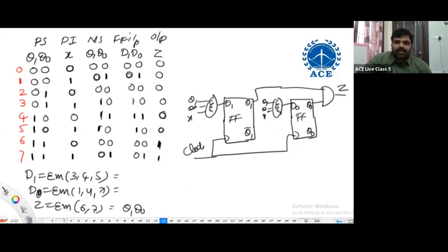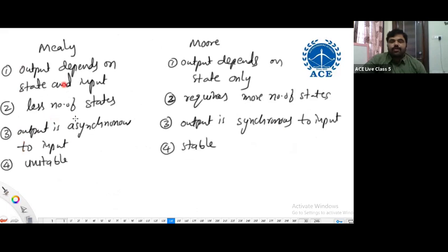For example, if X gets noise from an external input, then obviously the output gets affected in Mealy. Whatever noise is on X can affect the output, which means it is unstable. But Moore systems capture what is on X only at the clock occurrence, so it is stable.